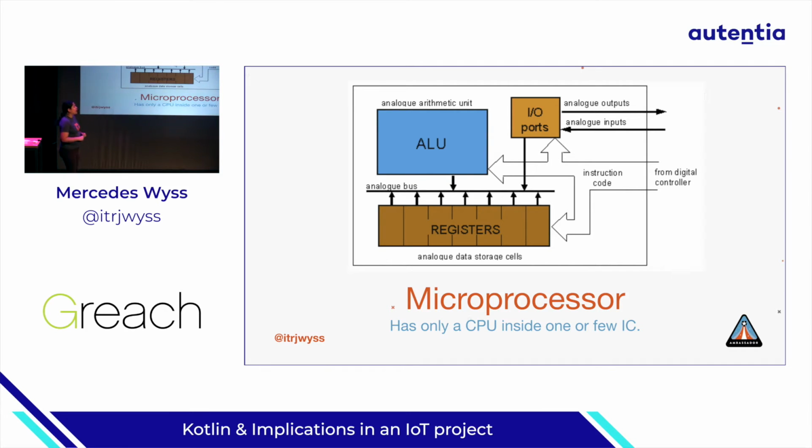Other things that happen a little bit here: for example, with a technology like Raspberry Pi, I can only use digital sensors, but I cannot use analog sensors like happens with Arduino. And the other thing is that sometimes the GPIOs in a microprocessor are not so fast, so some sensors don't work with them, and we need to use technology like Arduino microcontrollers to use these sensors.